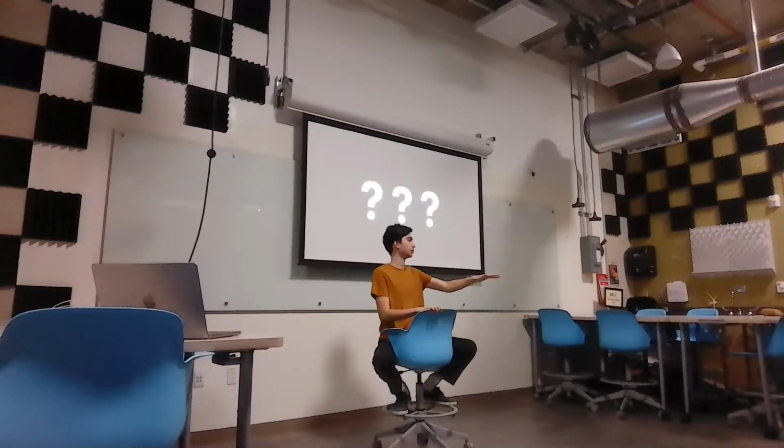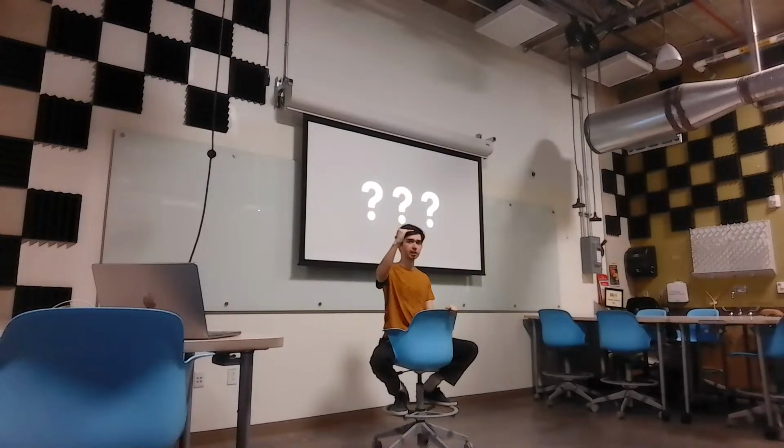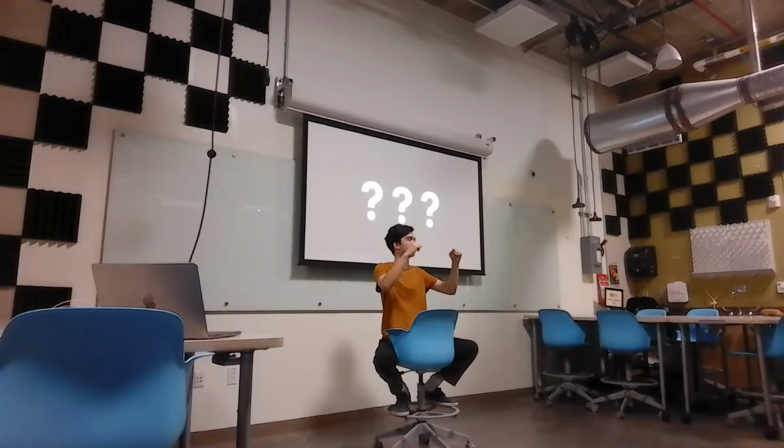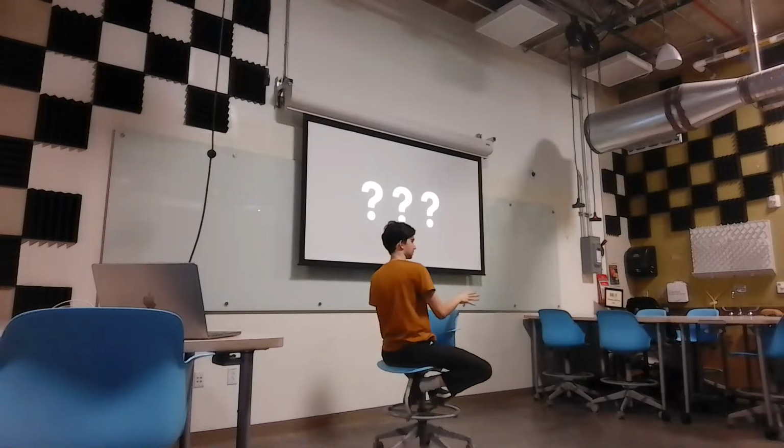But if we don't jump between them, we just go to the closest one, you'd see that as the battery voltage changes, the light would get brighter, brighter, brighter. You'd see it step between them, right? If you jump between them, it'll stay looking like constant brightness. Does that make sense? That's actually what my first firmware version did.